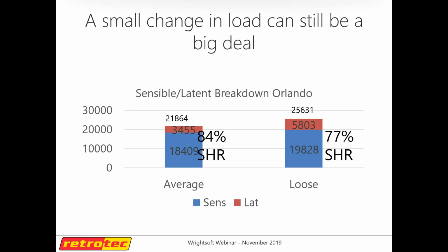Any idiot can handle the temperature. A bigger system handles temperature. The problem is it handles temperature without satisfying the moisture load. And so we have to pay really, really close attention to that latent load. And where does 3/4 of that load potentially come from, or at least over half? Infiltration. So, yeah, you want to chime in here?